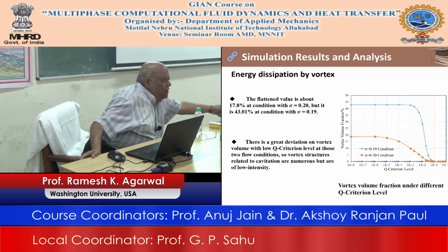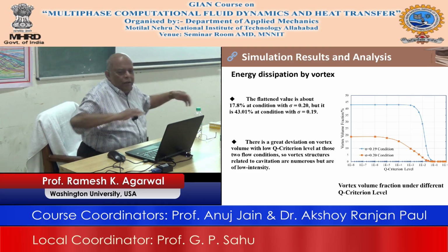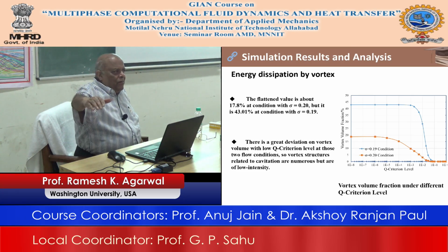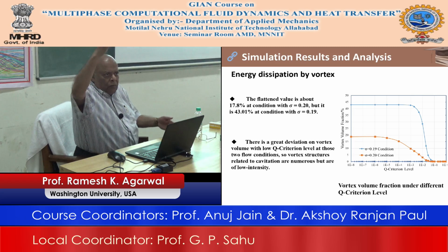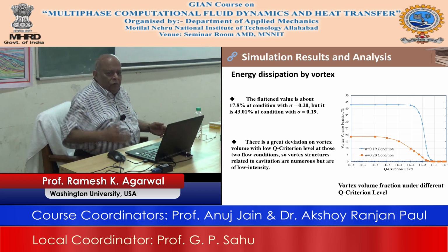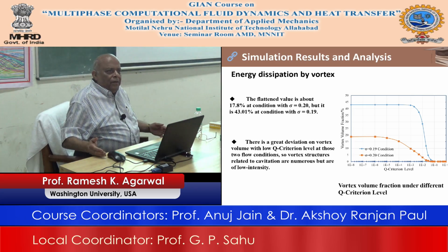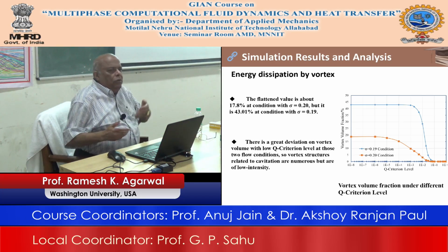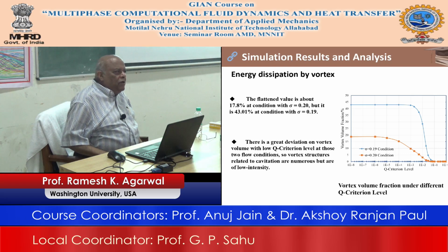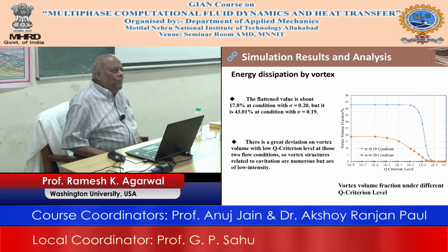How much is the boundary layer thickness there? 0. And here it will be delta, some function of Re. So if you calculate this vorticity, the profile will keep on changing because there is a delta here, Q will keep on changing, and then you plot Q along the surface. It will be very instructive, very useful.